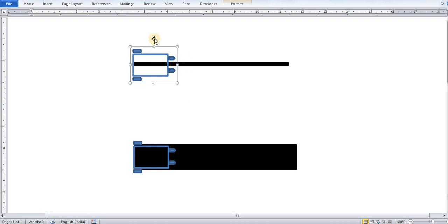Let's assume that because of some reason our robot turns, and now if you see, it is the left sensor which is on the black line, and that indicates that I need to turn back to the left, so that the left sensor goes into the white area again and we are on the path again. So if my left sensor is showing black while the right sensor is showing white, I need to turn to left to come into the right position.